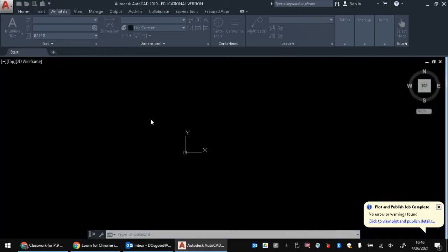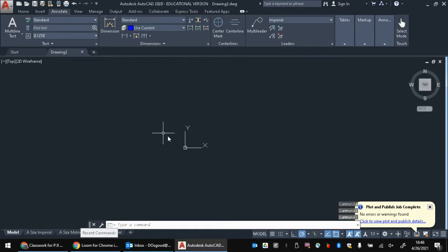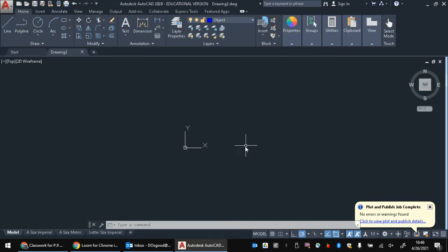that means. So if we start a new file here in AutoCAD, and right now we're just in the typical top view, what you probably haven't realized yet is you can rotate the view in AutoCAD. This really is secretly a 3D space, even if you don't know it. So what I'm going to do is hold Shift on my keyboard, and click and drag with the middle mouse button. And this is going to allow me to rotate that view.